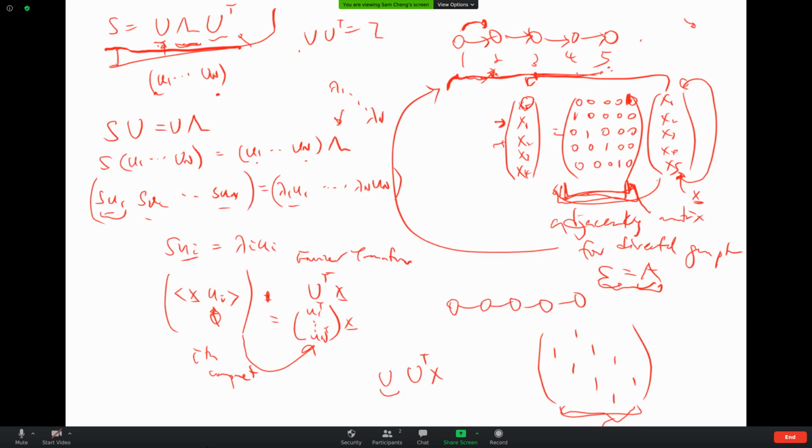Now when I want to do a kind of filter, for example, in the sense that you think of a low pass or high pass filter, the basis here, of course U1 up to UN, they can have bases of different frequency. For example, if you look at the classical case here, I may have some bases with a lower frequency and some bases with higher frequency. For the signal projected to this high frequency basis, I can just set it to 0. Like I have a low pass filter, I will set it to 0, or say a small value, and when projected to the Fourier basis with low frequency, I will just keep it there, then I will get a low pass filter.